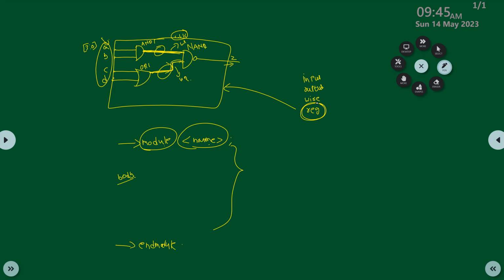But let's say at the output, in the same circuit, you are using a flip-flop and a clock is coming somewhere. CLK is another input, this is D, let's say this is Q. So now you cannot declare Z as just an output.